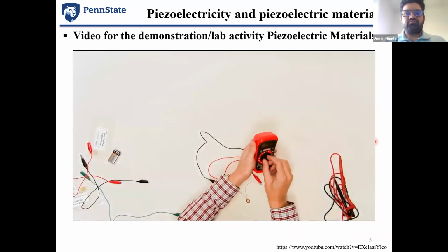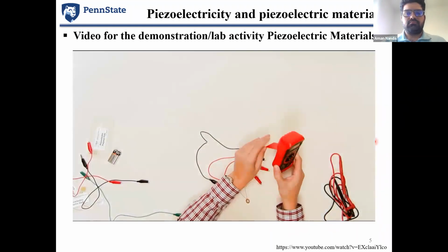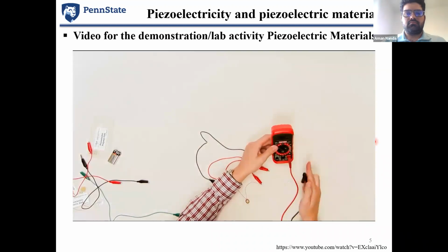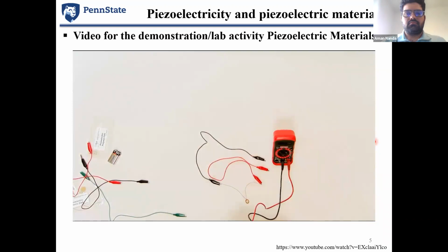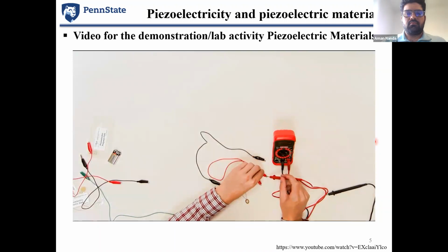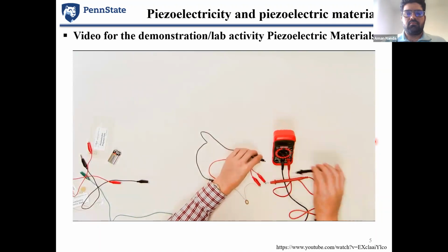If time allows, an additional activity with the materials can be performed with a voltmeter in place of the LED to measure the voltage generated by the piezoelectric. This provides a better indication of the piezoelectric effect, as the light generated by the LED is very minimal.